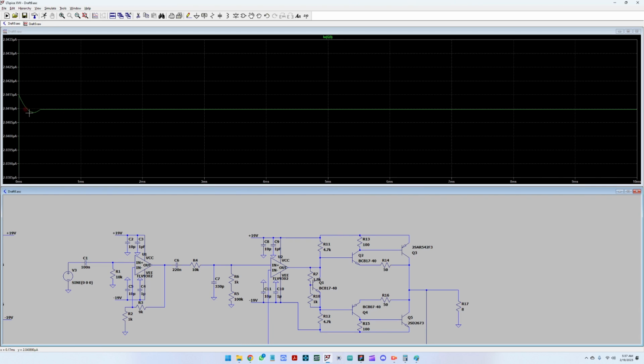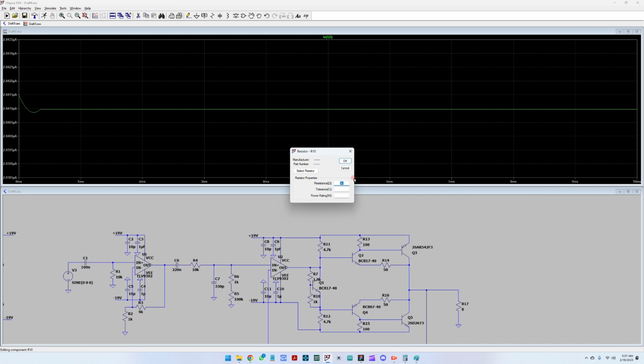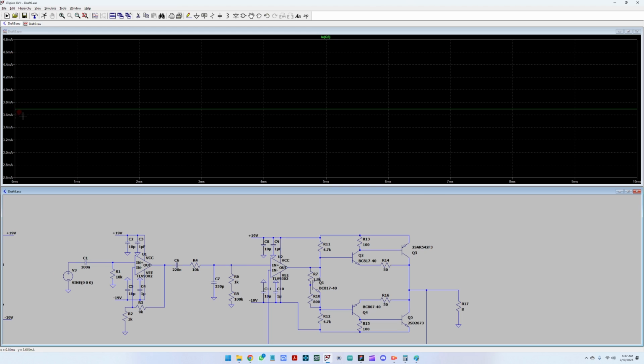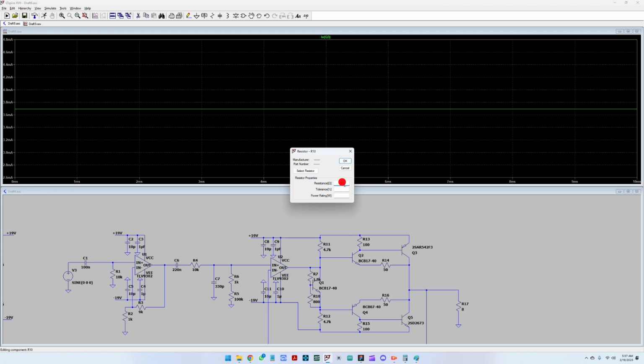Okay, so this means that at 1 kilo, this is not done yet. It's 2.5, so this is too low. Let's go to 800 ohms now. At 800 we have 3.7 milliamps, which is quite good. I think we can go a bit lower, so about 700.